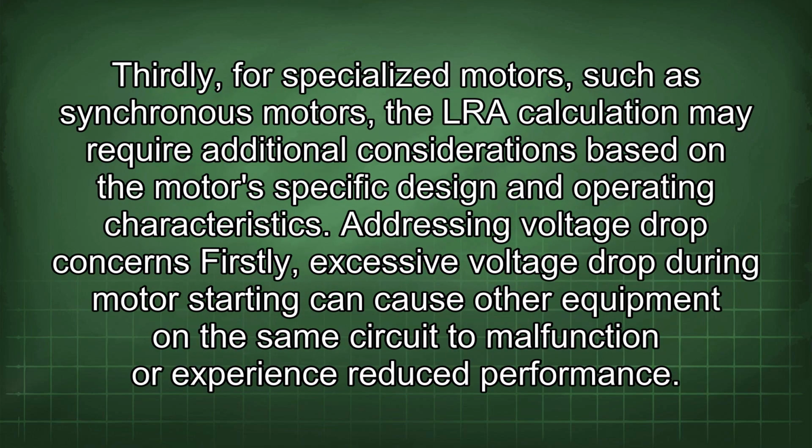Thirdly, for specialized motors, such as synchronous motors, the LRA calculation may require additional considerations based on the motor's specific design and operating characteristics. Addressing voltage drop concerns. Firstly, excessive voltage drop during motor starting can cause other equipment on the same circuit to malfunction or experience reduced performance.